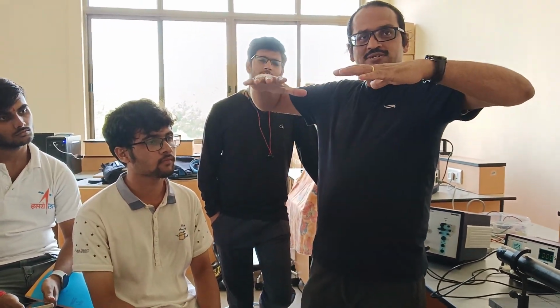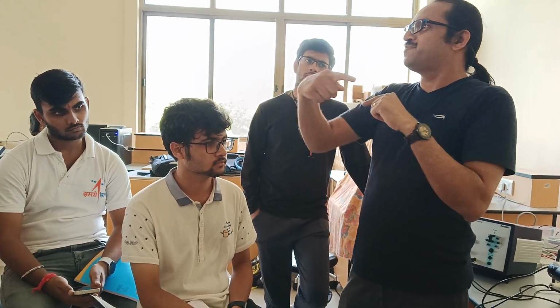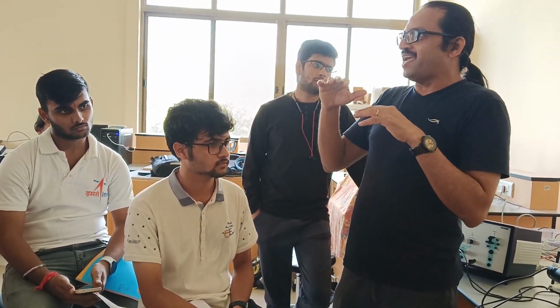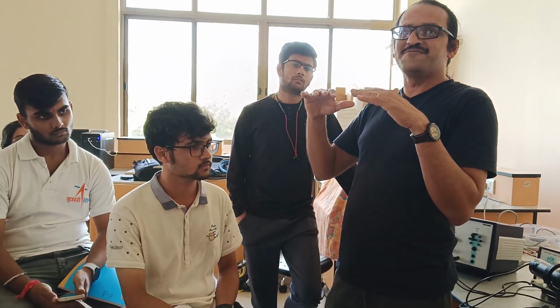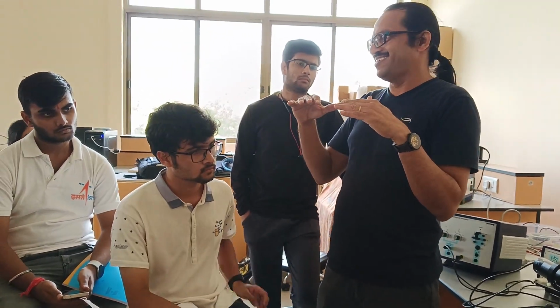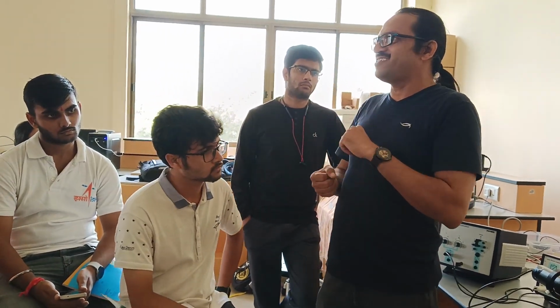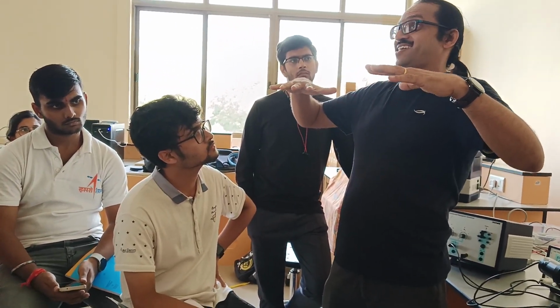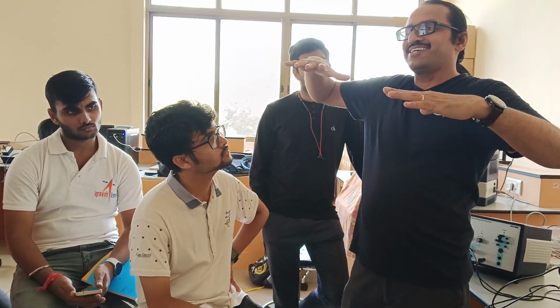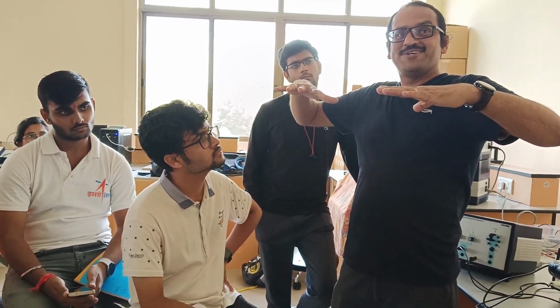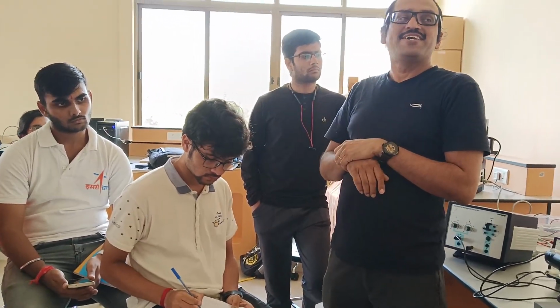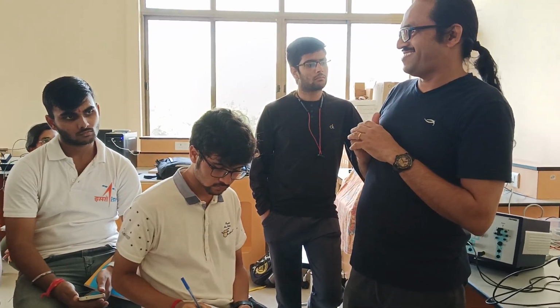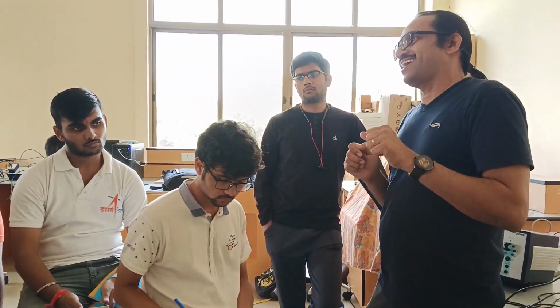You use this. The full accelerator system is mounted on blocks, very thick legs. Underneath each leg there are piezoelectric drives and a beam of laser interferometer going. If any of the structure moves even by a micron or less than a micron, a feedback circuit sends voltage across the piezoelectric crystal, and the whole structure is dynamically corrected. Because this reaction keeps happening for months, if not years, there is no time to stop and correct it.